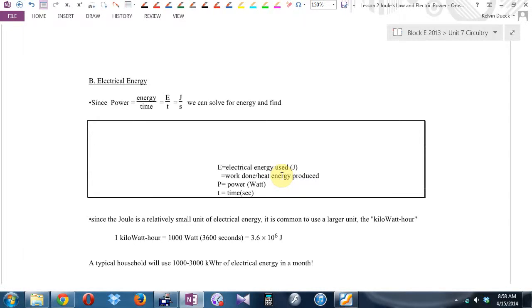Now, some natural gas systems can heat up almost as fast as it drains, not quite, but they can last longer. You'll see in the commercials, you'll have almost indefinite hot water. What they really mean is, if you drain this, let's say, we can replace it at about 80% of the rate that you drain it. So it's going to run out eventually, but it's a lot better than a trickle electric heater.